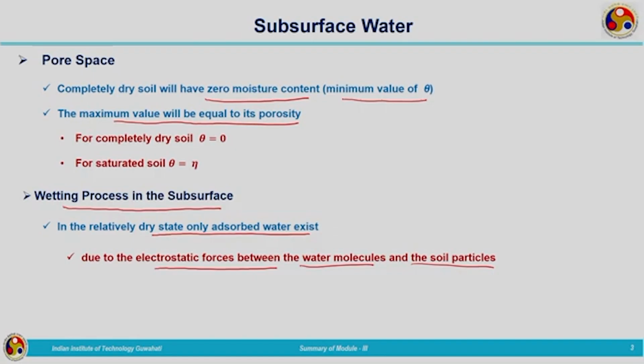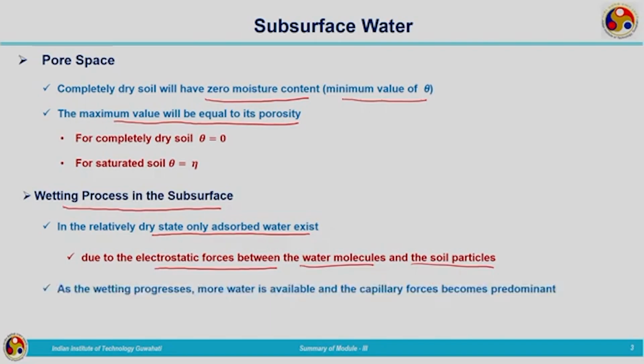When rainfall or infiltration, or perhaps some agricultural activity, takes place in the soil, then wetting progresses and more water is available. At that time the capillary forces become predominant. So, when the relatively dry state becomes wet, as some water infiltrates, the capillary forces, that is the suction forces, come into the picture.